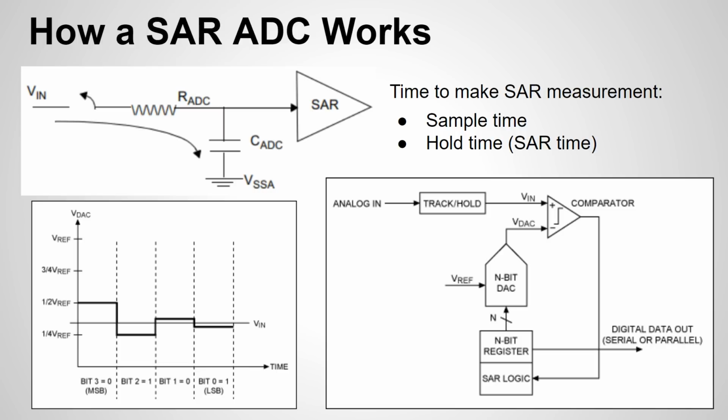So let's say minus is ground and plus will be whatever the reference voltage is, or the max ADC input value. That's what will come out of this comparator. We'll think of those as ones and zeros. So a saturated op amp to the high power rail, or the positive power rail, represents a 1. And driving it to the negative power rail represents a 0. And that's actually how we create our 10-bit, 8-bit, or 12-bit string of binary values,